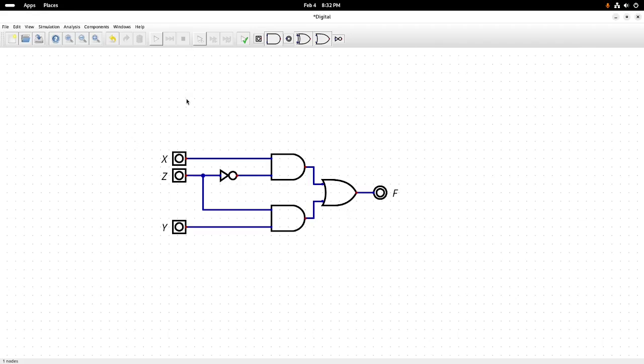So because gates have delays in when they transmit, this path right here has a longer delay than this path, and that can cause the output to just blip really quick, even if it is a nanosecond. And a nanosecond, who cares? It's a very short amount of time.